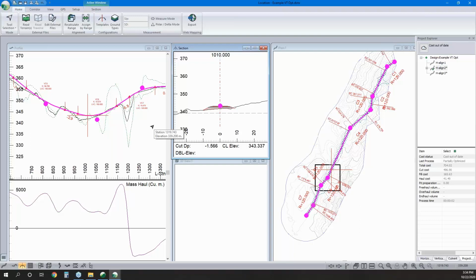Maybe. We do have a resident expert in-house who does a lot more work with Civil 3D, but I believe it's a plugin called Export Corridor. It creates something called a CSX file, which samples your cross-sectional behavior in your assembly, plus or minus 10 meters or whatever you define, and then we can bring that series of behaviors into the software so that as the optimizer moves it around, it has an idea of what the cross-section is going to look like at those different positions.